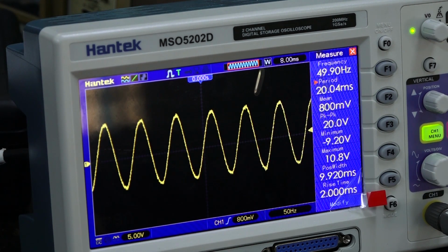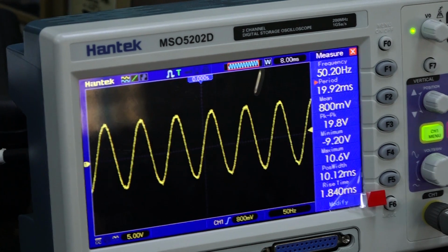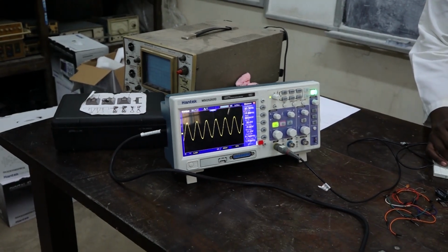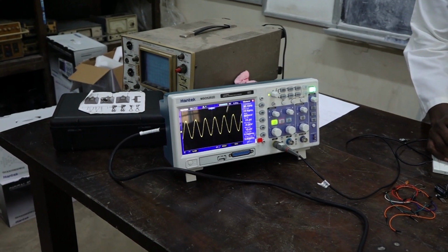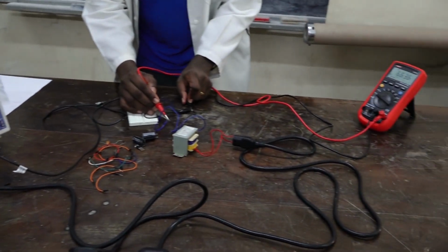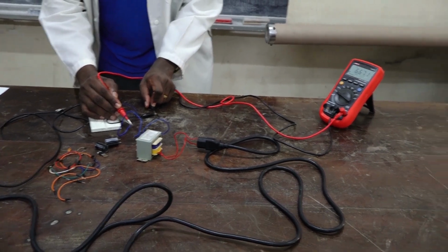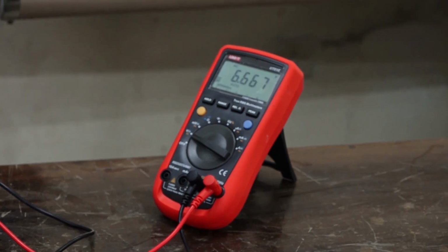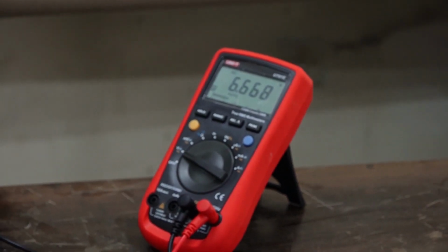When we moved into the practical, using the digital multimeter, if you remember, we measured the output root mean square voltage as 60.6072. And now I'm measuring it again: 60.671. Are we together?